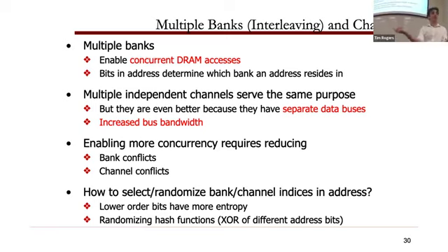We're going to do a similar thing here, except instead of mapping it to sets, we're going to map it to all of these different components. We have to map it to channel, to bank, to row, to column. So we're going to have some bits in the physical memory address, again the physical address, that tell us which of the components this thing is going to live in. And this greatly simplifies the memory controller's job. Because remember, it's the memory controller's job to take this address and tell you where it is. If it's some dynamic mapping, that's expensive. So I'm just going to take a static mapping and do that.